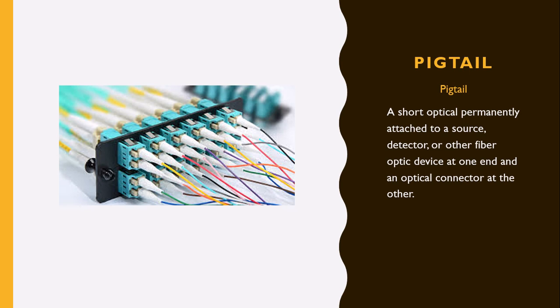A fiber optic pigtail is a fiber optic cable terminated with a factory installed connector on one end, leaving the other end unterminated. Hence the connector side can be linked to equipment, and the other side can be fused with optical fiber cables. Pigtails are utilized to terminate fiber optic cables via fusion or mechanical splicing.